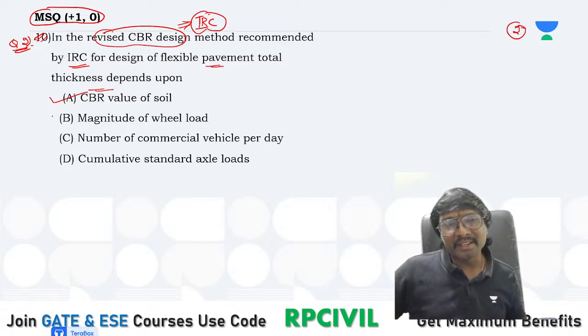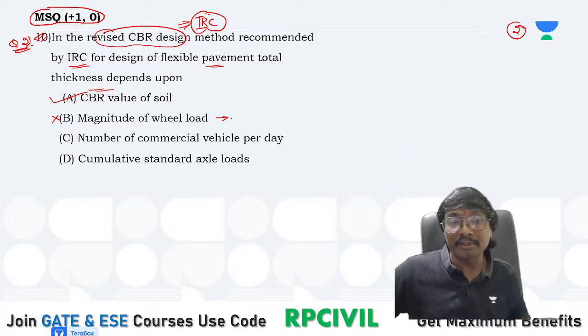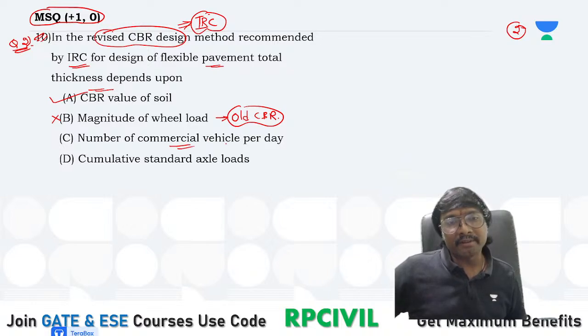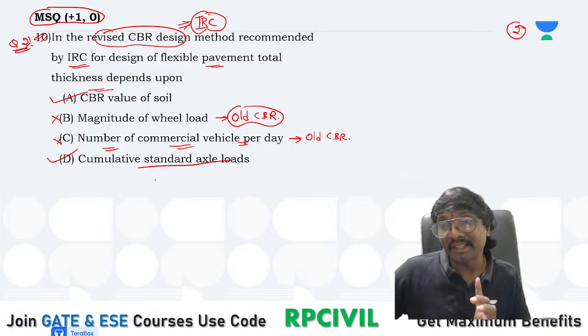Does the magnitude of wheel load come into the picture? No. In that old CBR method, this is useful. That is your old CBR method. Now, number of commercial vehicles per day, are we using this directly? No, no. This is also in the old CBR method. Now, only cumulative standard axles, these two values, we are using in the new CBR method.